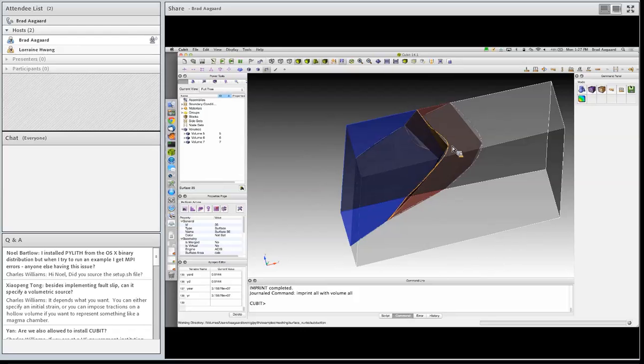And so what oftentimes we'll do is we'll take that to extend our surfaces further than in areas where they may be defined. We'll usually take points and project them either down along a contour or vertically, or in some way we put artificial points. Sometimes we may do two points instead of a whole curve. But if you want part of that curve, then it's going to influence the rest of your spline surface. So you need to be careful how you treat the edges.